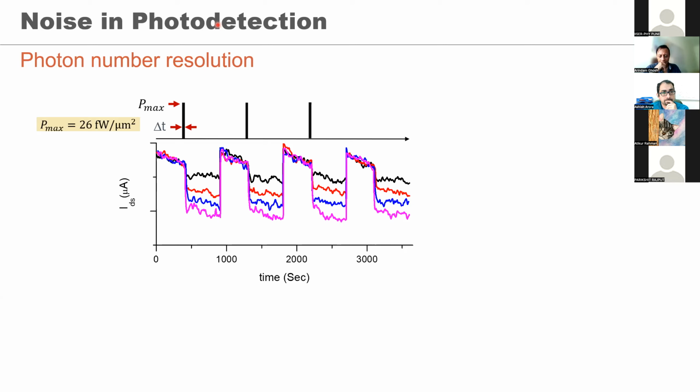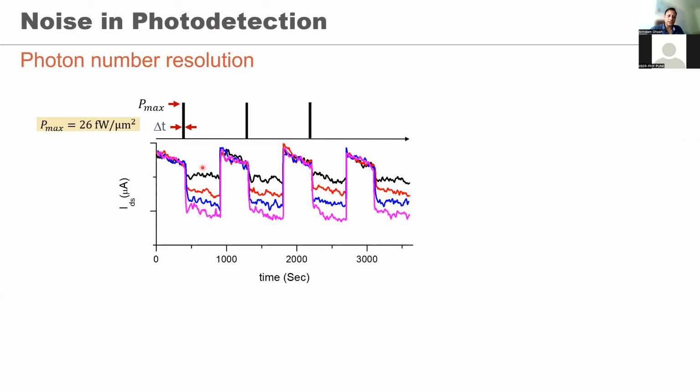Now, why is there a very sharp rise again? I'm a bit confused about that part. Oh, you mean here? Oh, okay, very good point. Sorry, I didn't say that, but you're absolutely correct. When you shine light here, the electrons jump out of the chalcogenide layer and go into the graphene layer, and the graphene was initially hole-doped. So when you transfer electrons there, the effective carrier density decreases, and the current through graphene decreases, which is why it's a negative photoconductance.